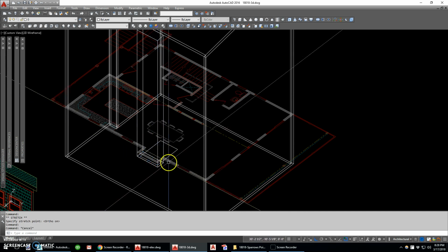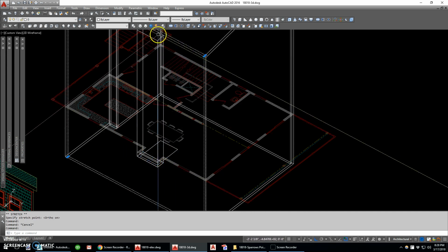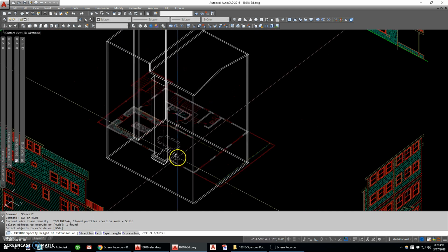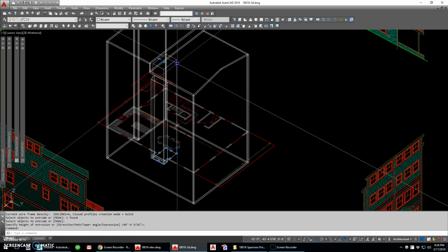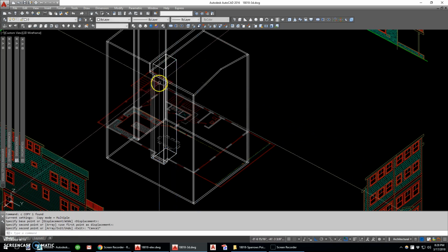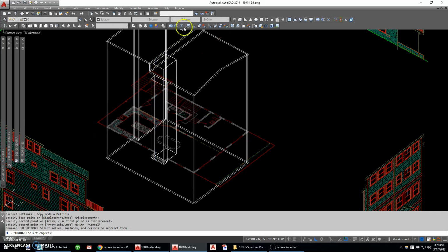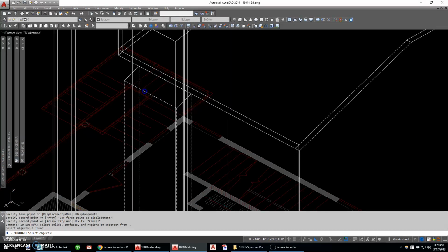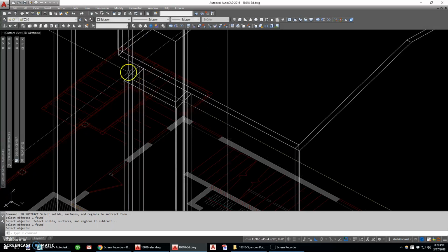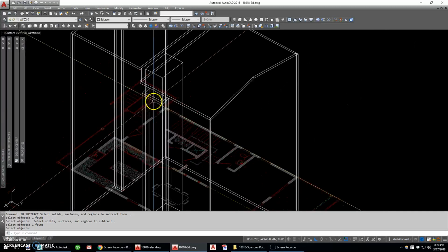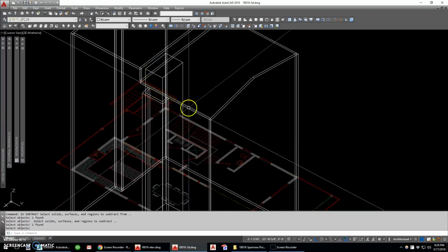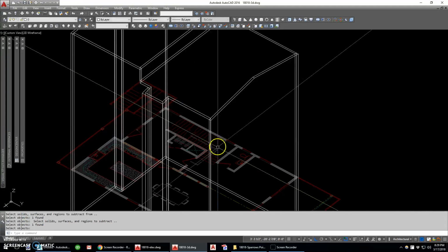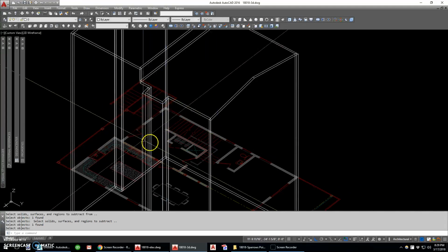I also want to subtract that out of this wall so this wall doesn't play through. So what I'm going to do is extrude that. I'm going to go quick here because my 15 is ending. I'm going to extrude it up. I'm going to copy it over itself. Then I'm going to use the subtract command, which is again up here, subtract. I'm going to say I want to subtract from this object and pick that box, which there are two. Now you can see it made me a hollow object. Now I want to subtract that same object from that outside wall. Bam, looks cool. I'll see you in the next video.